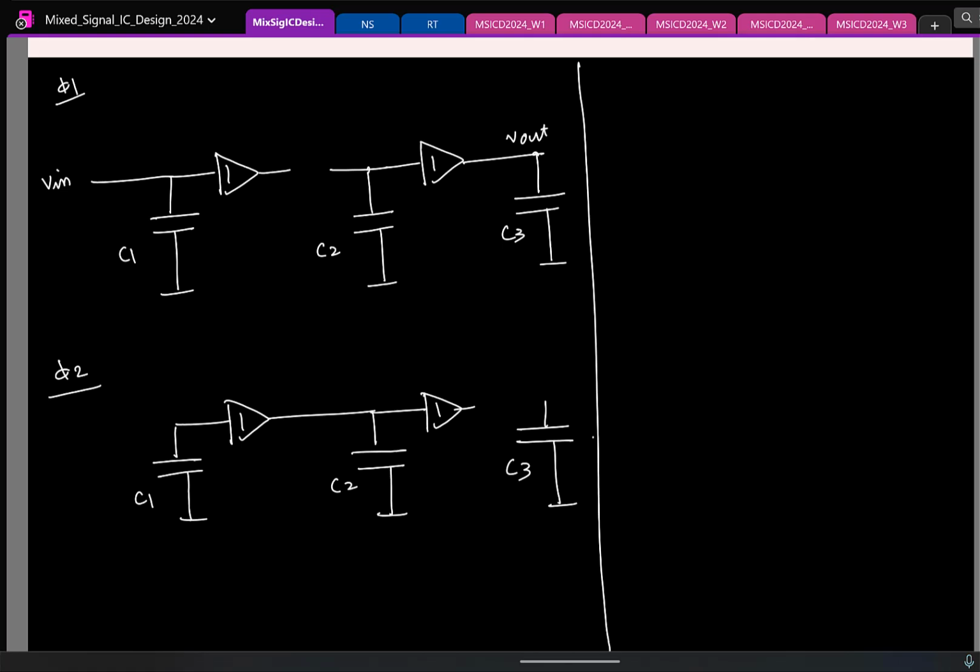Okay. Remember that? Okay, hold on. Can others try and tell me if you can write charge conservation there? Which one? C2 and C1 meaning? No, what I'm asking is you're interested to find V out. So it makes logical sense to choose this node and write KCL or charge conservation. So if you try to write charge conservation at this node, what all will you take? Remember that KCL, so you look at the delta Q here, which means I'll consider the charge on this plate. But what about the current here? That is something that you do not know.